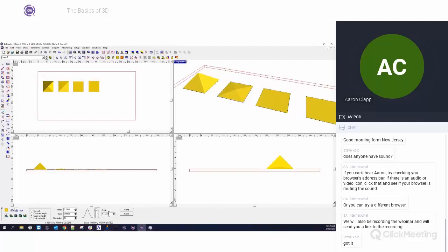So despite whatever angle that I put here, the relief is going to be created at a specific angle. So it's going to be created at 67 degrees, but the software is then going to scale that down so that it gets squished into 0.75 inches. It's a very, very subtle thing, but your results could look quite a bit different.